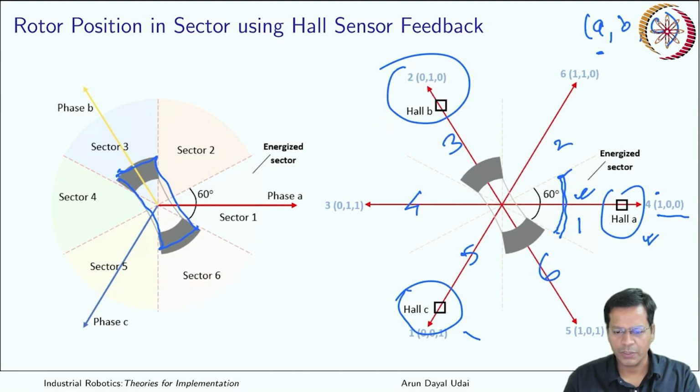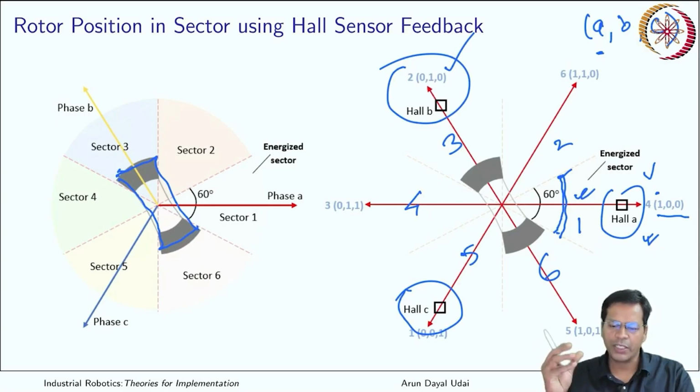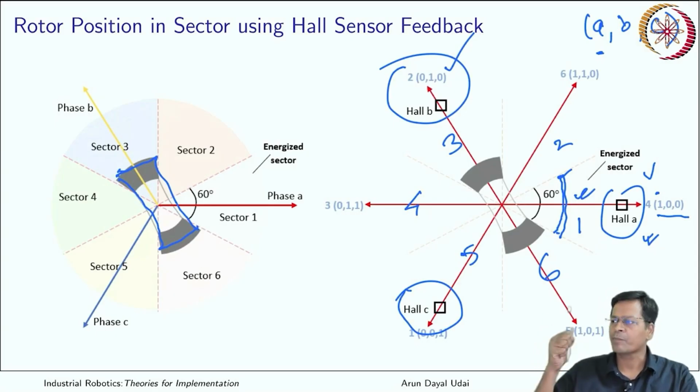you are in sector 2. So what will happen? The nearest region is this one and this one, so both will turn high, whereas this is totally opposite. Hall effect sensors are mostly polarity dependent. If it sees the north pole of your rotor, that turns it high, the south pole will not turn it high. So they are sometimes directional in nature. These are one of those.